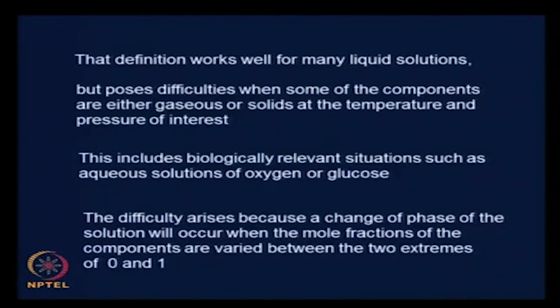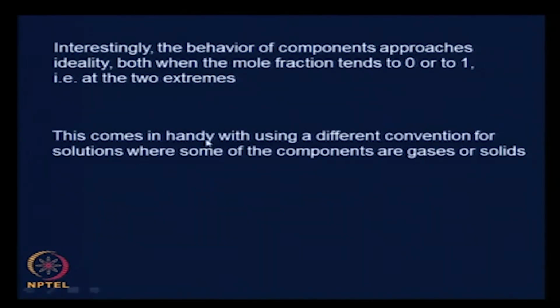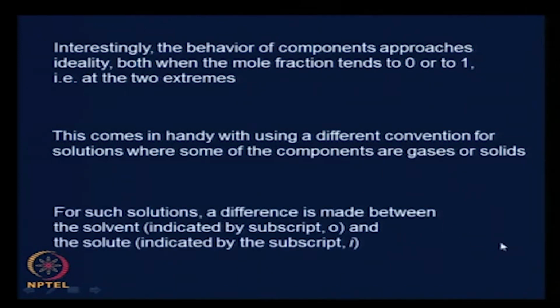The same formulation that we presented will not be able to handle that, and we did that by noticing that at the extremes, that is when the mole fraction either tends to 0 or 1, the behavior is ideal. We had used that fact, and then we had come up with a separate expression for the solvent and a separate expression for the solute. Both need to be used together in the model for chemical potential.